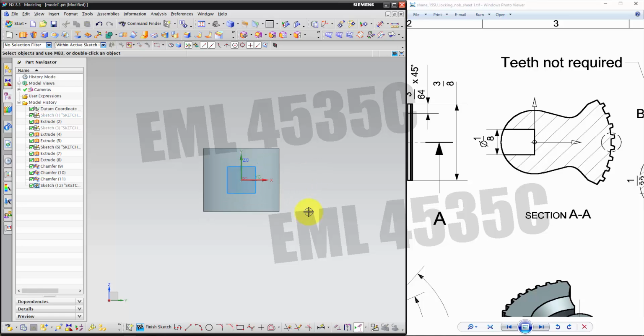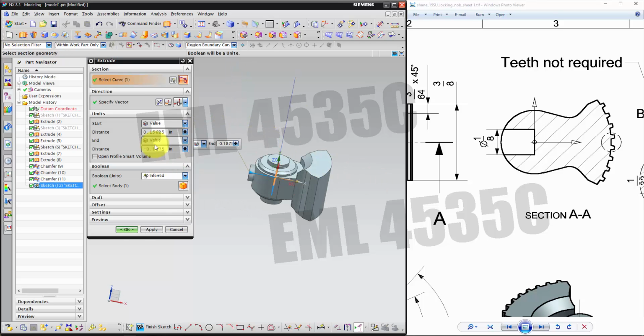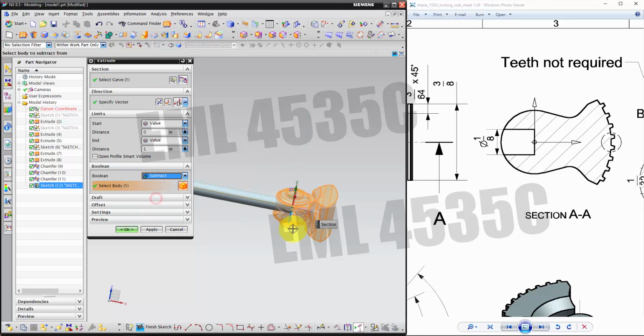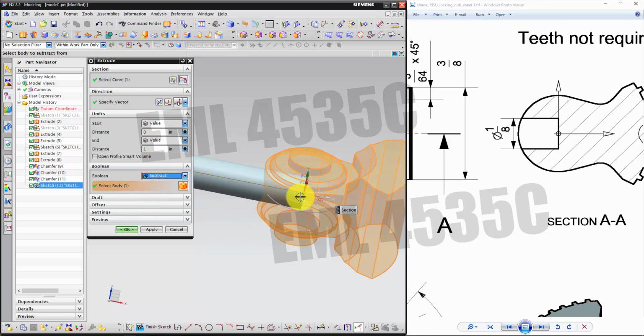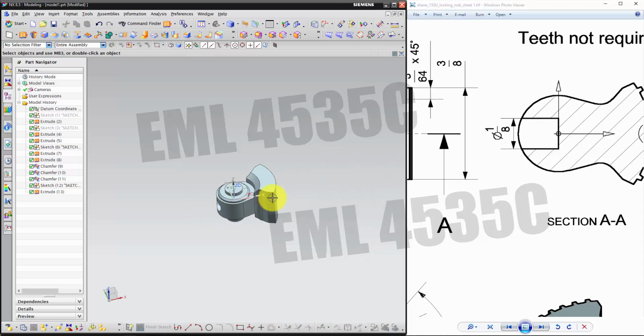So here's my orientation. The circle is 1/8. Then we can just go straight to extrude. Because this is a subtract, you can take a look at which direction you want to go. So one is definitely 0, as that's on the sketch origin. The other one could be big, and we'll reverse the direction and make it a subtract. So it doesn't matter how long you extrude, as long as this is longer than your part, then it'll make a hole in the middle.